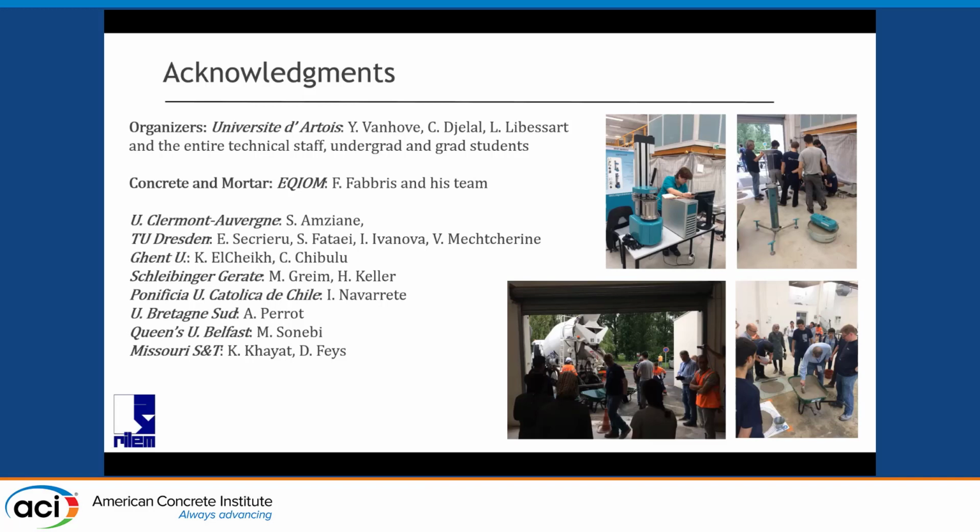Is it related? Because obviously we know that the less slump, maybe you're getting into a material shearing or so. Slump on its own is not going to tell the story. You got a slump of, let's say, 200 millimeters with a 0.55 water cement ratio, and you got a slump of 2 millimeters with a 0.2 water cement ratio. I'm much more confident on the 0.2 water cement ratio. Viscosity is much higher. So I'm much less likely to have a shear zone. The higher is that ratio, it's the ratio of yield stress to viscosity that really plays a role on how much material is being sheared. That's the one that plays.